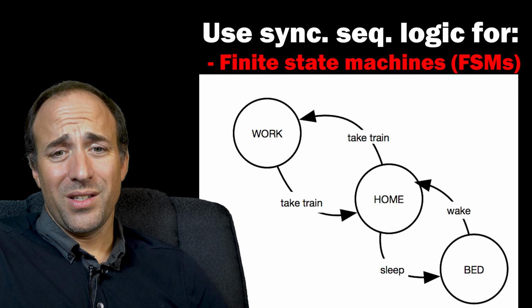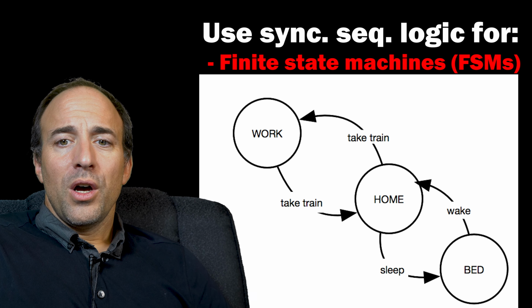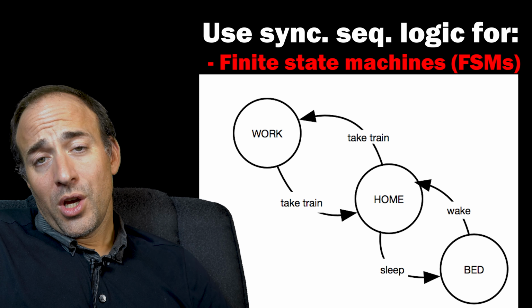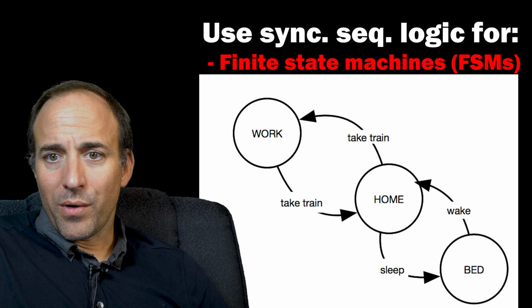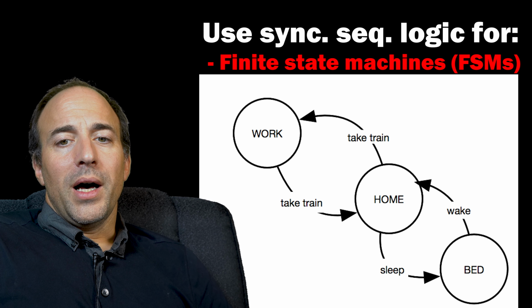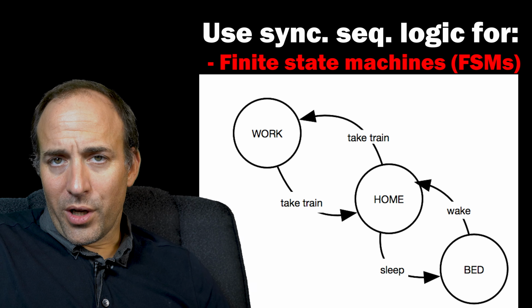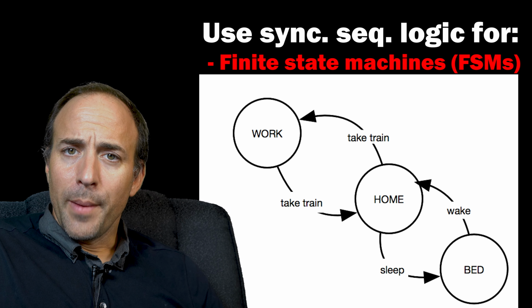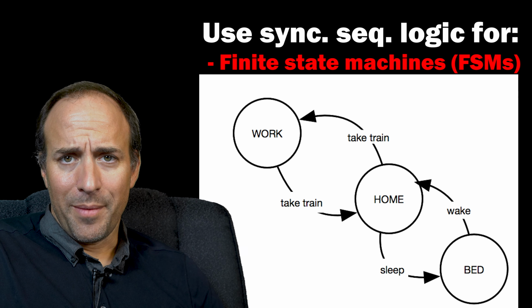Finite state machines, on the other hand, are essentially like having a Boolean expression that can change each cycle depending on the circumstances or depending on the sequence of inputs. They're useful as controllers, such as controlling an ALU that requires multiple cycles to perform an operation. In that sense, this would be referring to an ALU that might take, say, 10 cycles to perform a divide, but can only perform one divide operation at a time.